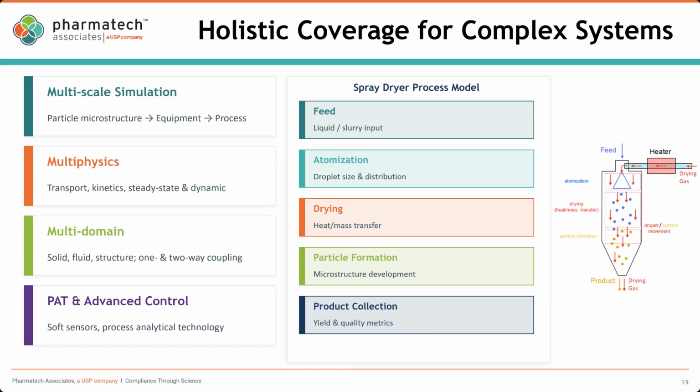distribution. Inside the chamber, these are not plug flow systems, so there is back flow and recirculation of the material that you are going to see in the next slide. These particles are going to interact with each other, with breakage and coalescence happening, altering the particle size distribution in contrast to the droplet size distribution that is formed. And all the way we go to the cyclone. Some of the D10 or D5 particles fly out from the different cyclones, depending on the geometry and the flow rate of the gas, and that would also change the final particle size distribution of the product.